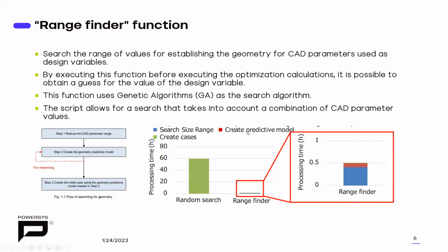Of course, this predictive model is based on already existing data, experience data. JMAG will create cases in advance. If you put very few cases in the learning model, of course, the guess of JMAG will be wrong. You need to put enough data in the predictive model, in the training model, and then JMAG will be able to guess correctly if the new set of parameters will give a correct, valid geometry or not.